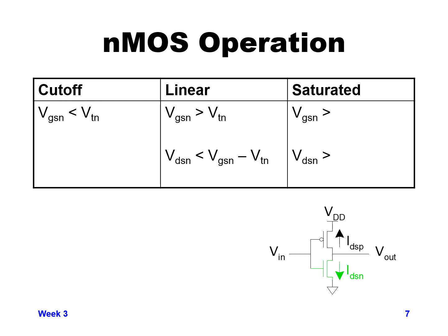So as long as the drain to source voltage is higher than the gate to source voltage minus VT, we're not in the linear region. But if the drain to source voltage is less than the gate to source voltage minus VT, which a lot of times is a fairly small voltage, then we are. If Vin is just barely over VT, then you have to go fairly far down before you're in the linear region.